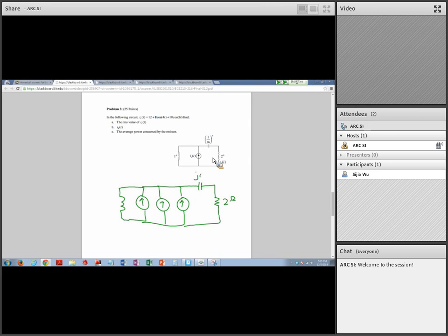This is j omega. You did it one by one, like DC, because they have different frequencies. Yeah, so for different frequencies, this would be j. The omega is different for different ones. For example, for the 12 amps, omega is 0, so these don't do anything. This would be a short circuit, that would be an open circuit. For 4t, you do each of them one by one, then you add them together.